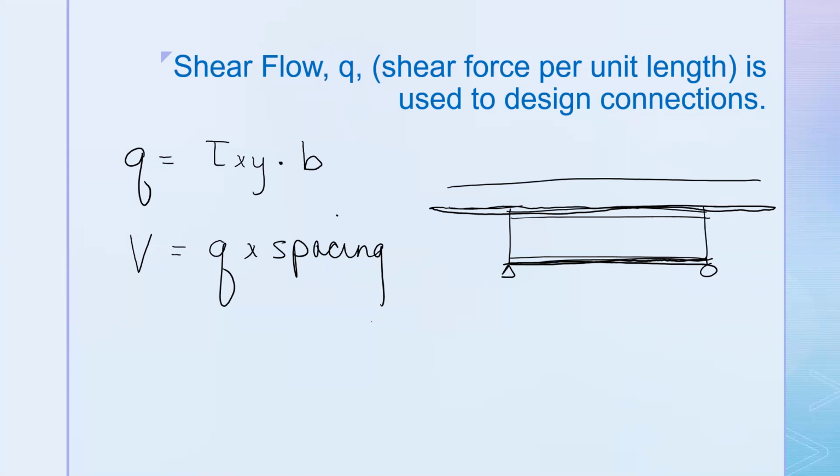So we have these metal pieces that come up like this. They're welded to the top of the beam. And then they are embedded in the concrete. So the beam is already in place with these shear tabs at the time when we pour the concrete. So therefore they end up inside the concrete. And then the two have to act together. You've created a composite beam.